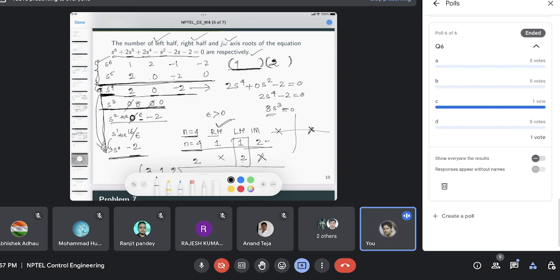First analyze this auxiliary polynomial. From S4 up to the end, you see that only one sign change has happened. That means only one pole of this auxiliary polynomial is in the right half plane. And you know that the poles of this auxiliary polynomial are located symmetrically around the imaginary axis. So there should be one left hand pole located symmetrically to this right hand pole. So there are 2 remaining poles for this auxiliary polynomial, and they must be on the imaginary axis, because right half and left half poles should be in pairs, symmetrically. So you should have 2 imaginary axis poles.